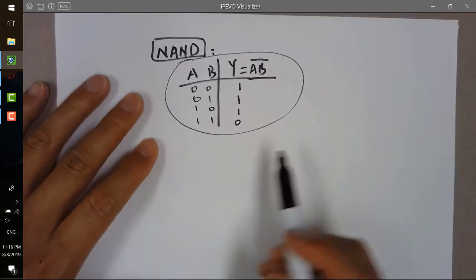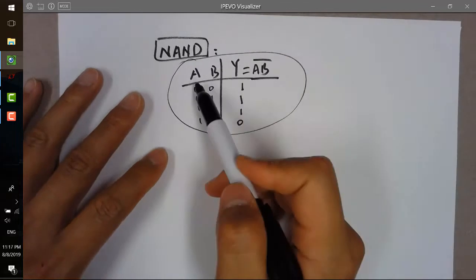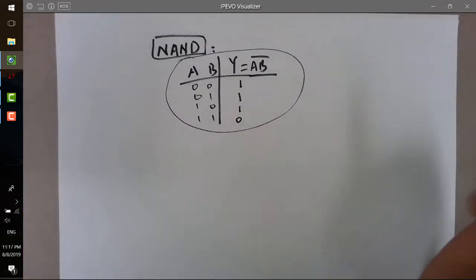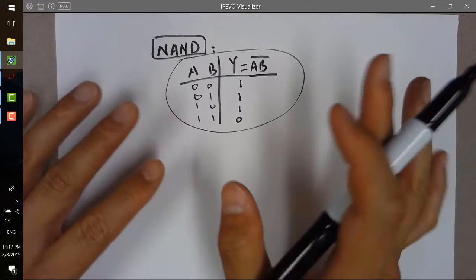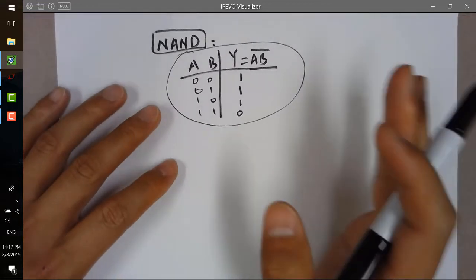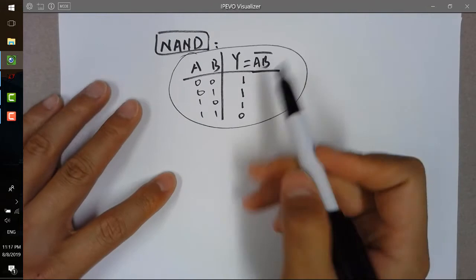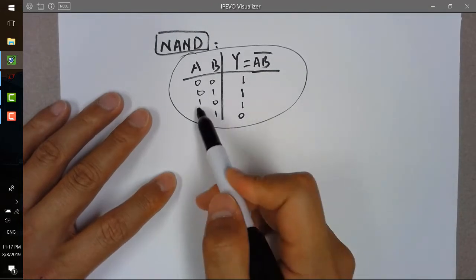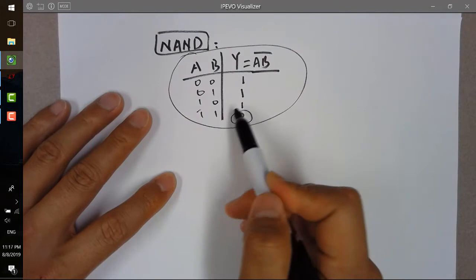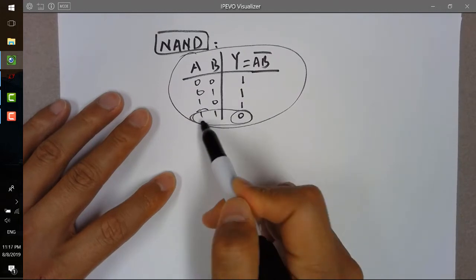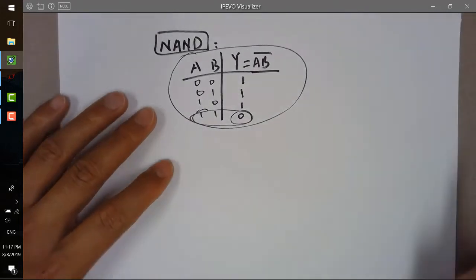All right. So before we do anything, we know there are two inputs, so we need at least a pair of NMOS to implement something. Now let's take a look at 0. When the output is 0, we need both A and B to be 1.